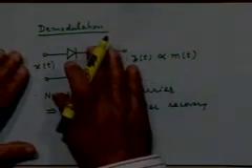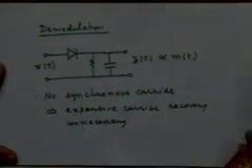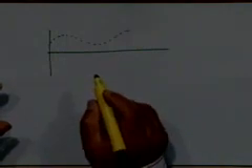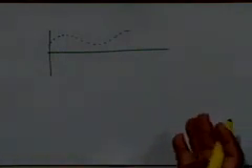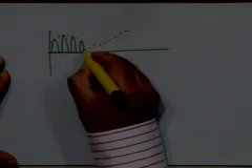You can think of this action as some kind of a rectification action, but more precisely we will see what is happening. So obviously we only need to look at the positive half cycles of the carrier wave. The negative half cycles we cannot make forward biased. So we only necessarily make it reverse biased, right? So we only need to understand what is happening during the positive half cycles of the carrier wave. Is that okay? You agree with that?